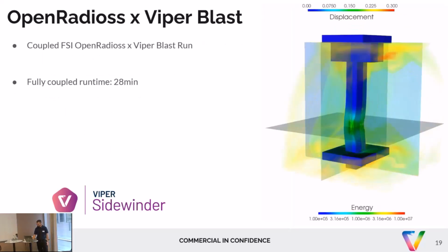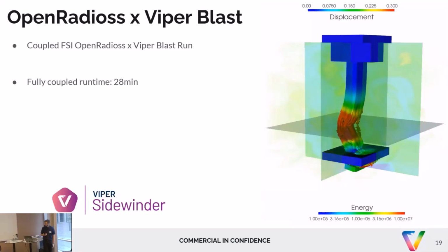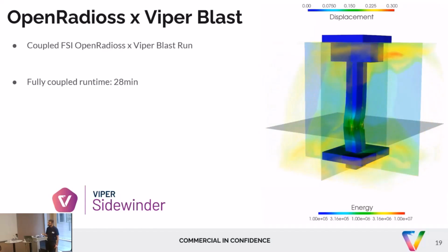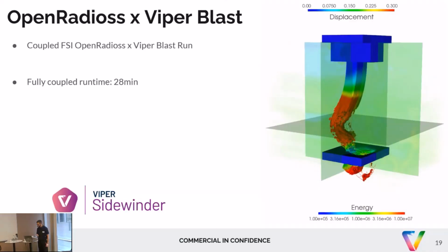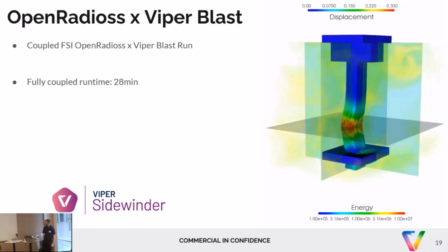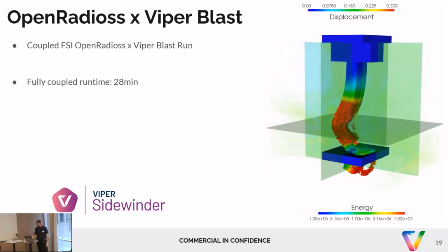Or we can run a fully coupled simulation, and on my laptop, it just took 28 minutes to run. And this is equivalent to the longer starter time, because we are passing information back and forth. We're not doing any decimation. We don't have any assumptions on interpolation. So this is more akin to the 23-minute time run, and we can do the fully coupled simulation in 28 minutes. And we can see how well the fluid reacts and how well the column gets destroyed.